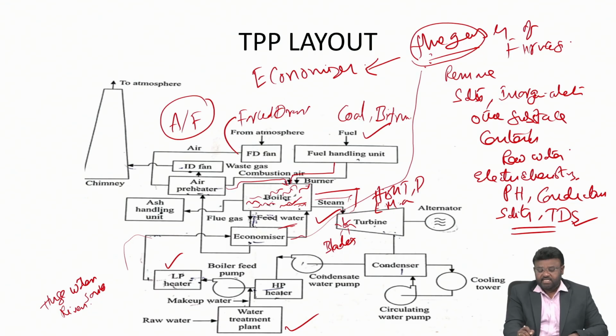Another thing is that the steam, upon generation, will be cooled by sending cooling water onto the turbine system and turbine pipelines. There the steam will be cooled down and becomes water. This water is nothing but condensate water. Without wasting any of the condensate water, we have to recirculate it and add it up with the raw water.